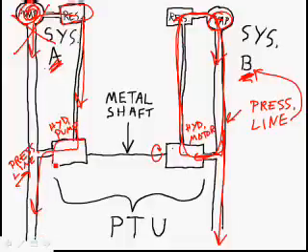Now this hydraulic pump is set up, it's not nearly as big as the main pump for that system, but hey, I'd rather have a little bit of fluid at a pressure than no fluid at no pressure at all. And so of course here you can see this makes up the power takeoff unit, the power transfer unit. You could also flip the switch in the other direction, because the inside of a hydraulic motor and the inside of a hydraulic pump is the same.